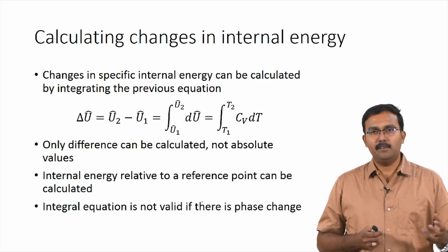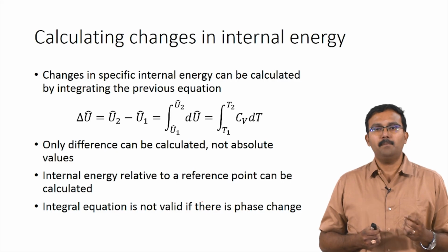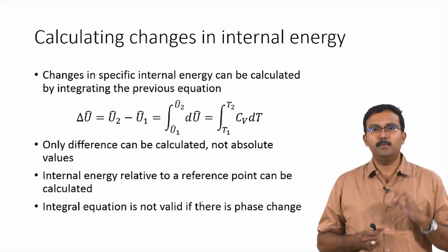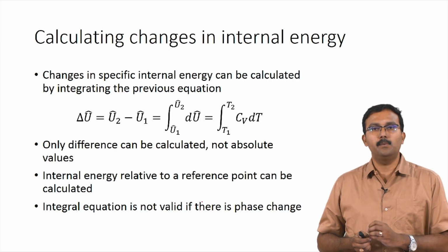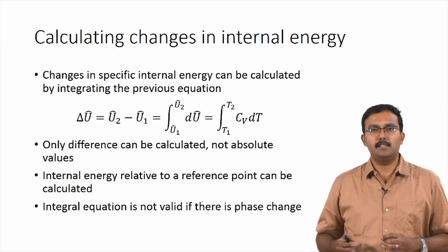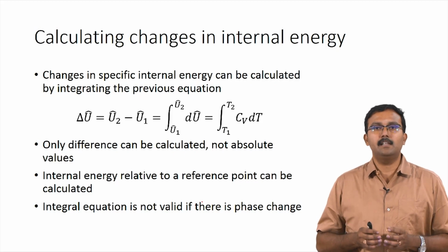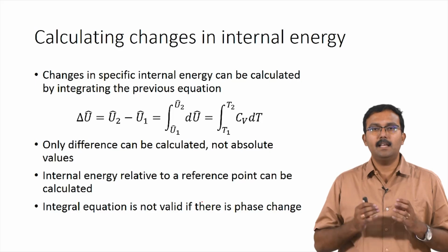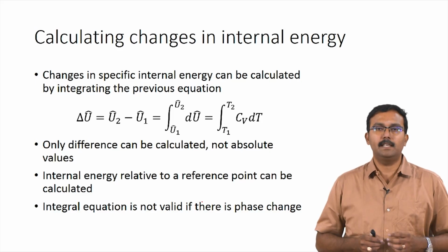The integral equation which we have given here will not be valid when phase change happens. This particular system we have assumed as a single phase system, and therefore, we can use this equation only when there is no phase change. If we have phase change, there is an inherent change in internal energy associated with phase change, and that needs to be accounted for separately, and it cannot be brought into this integration.